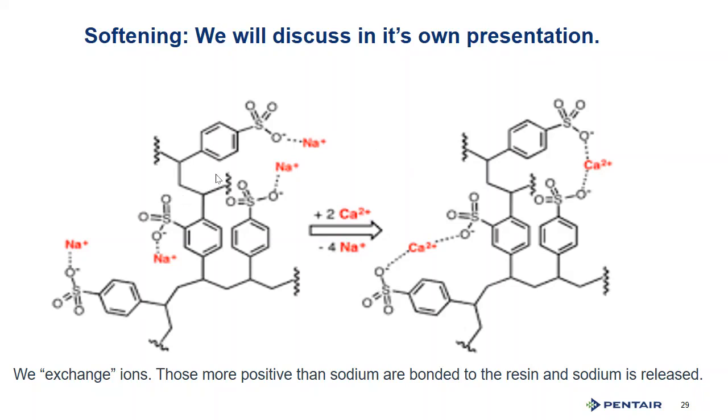So ion exchange is literally the process of on this resin bead. If you look at these squiggly lines, this is where the rest of this attaches to the bead. And it's all made up of all these chemical compounds. But the exchange sites are right here on this sulfonyl group for those that like chemistry.